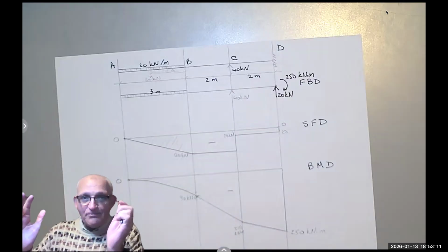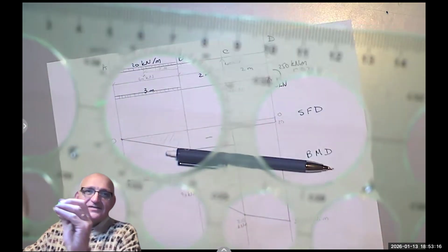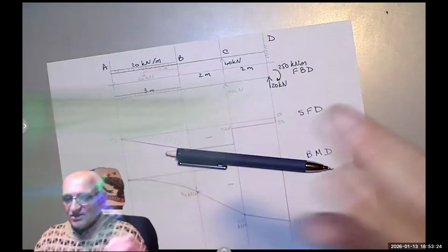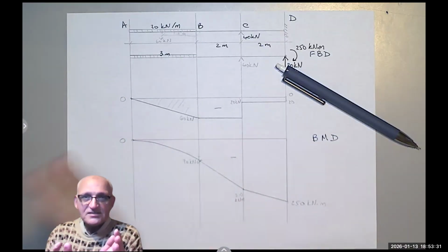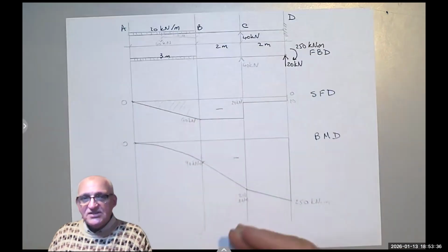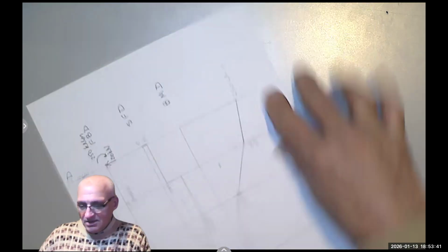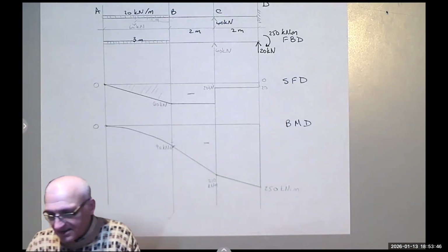So you see that the top fibers, like when I showed you before, can I make it horizontal? No, it's not easy, and I'm not going to break it. But when you turn it, you see that the top fibers are stretched and the bottom ones are compressed. So that's why we say negative. We draw it here. If you were following the British system, that would be a mirror image, you would reflect it on the x-axis.